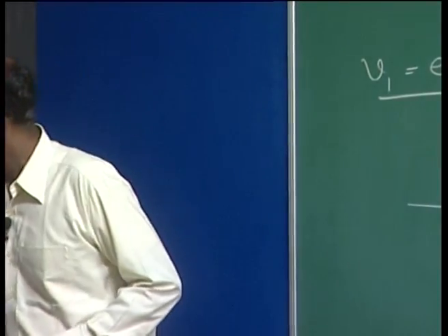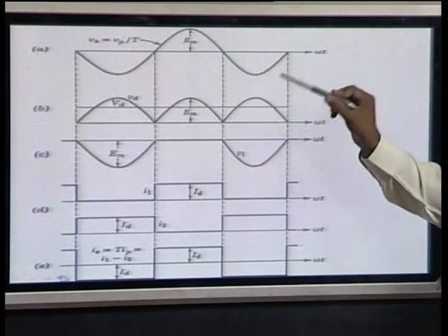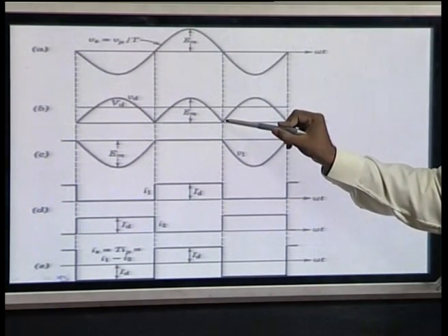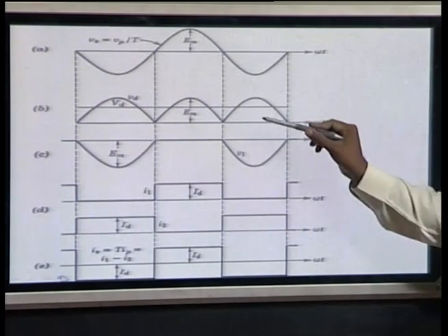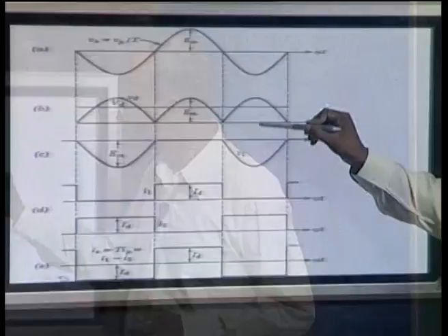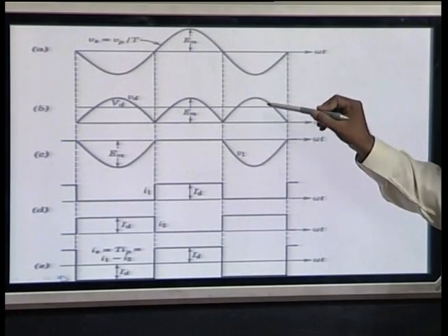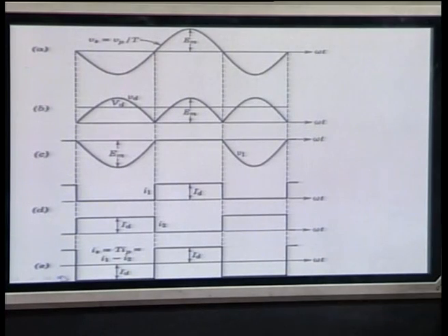Now, if you see the voltage which is going to appear across the various valves, let us suppose valve 1. In this case valve 1 and 2 are conducting, so the voltage across valve 1 is 0. Now, when valve 1 and 2 are off, the voltage is not directly this minus this. If you do this minus this, you will see it is twice of this, but here V1 can be analyzed by this circuit, the basic circuit.